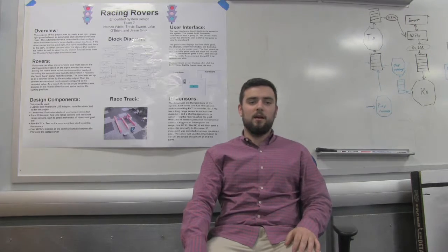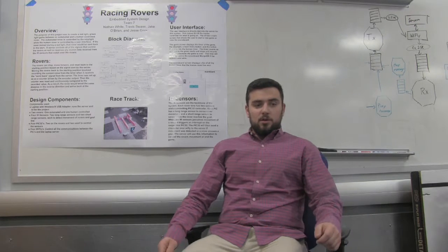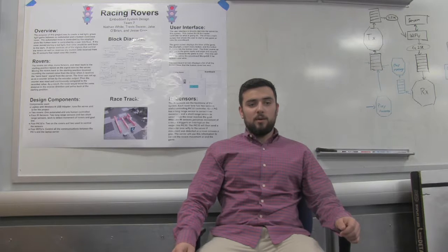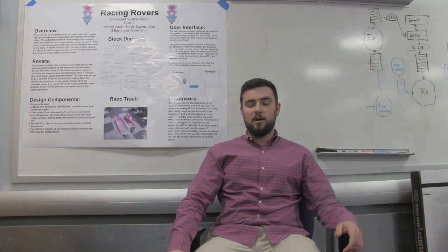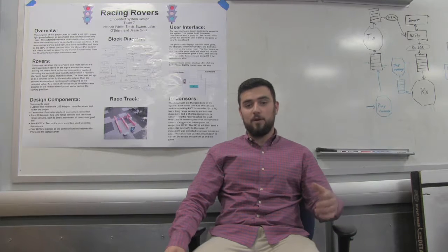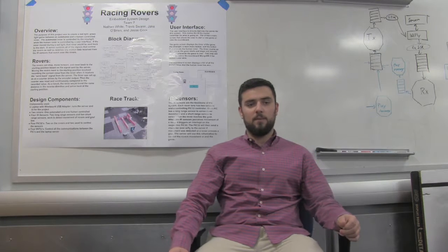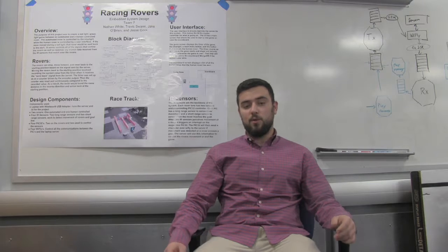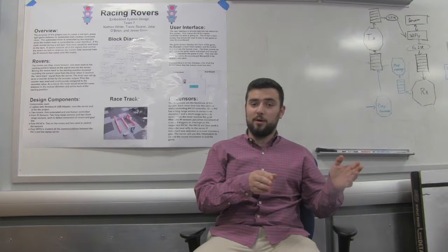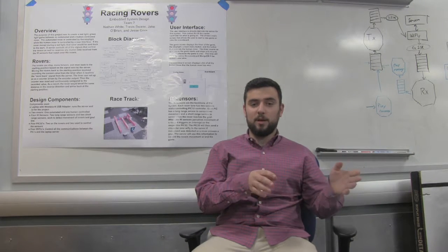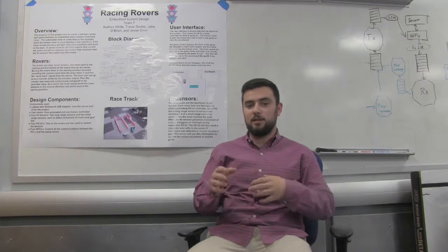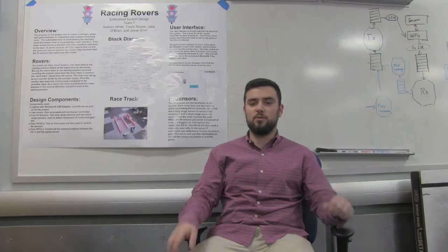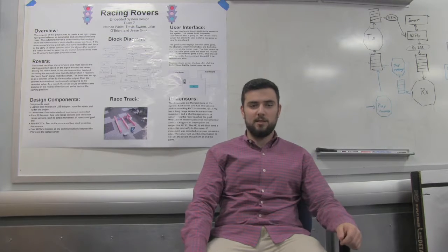As for the code, I used analog to digital conversion, or ADC, to get the data from the IR sensors. The way it worked is when data filled up the buffer in the PIC32, it would generate an interrupt, and that would send the data using a message queue to the main task.